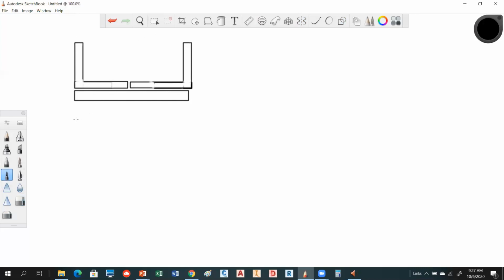This plate, usually a plate is indicated with a P through an L like that. Our plate is going to be 6 by 1 inches. So we've got a 6 inch by 1 inch plate. That's what this guy is. And this is called a leg or an angle. They usually call it like that, and then they'll say 3 by 3. In this case, we're going to have 3/8.